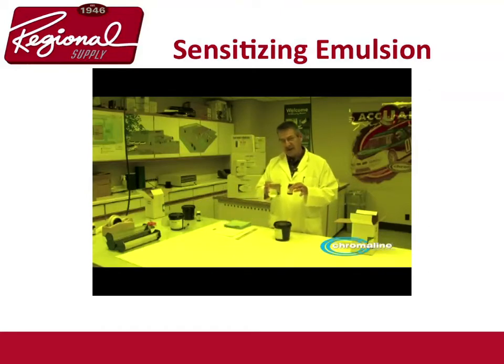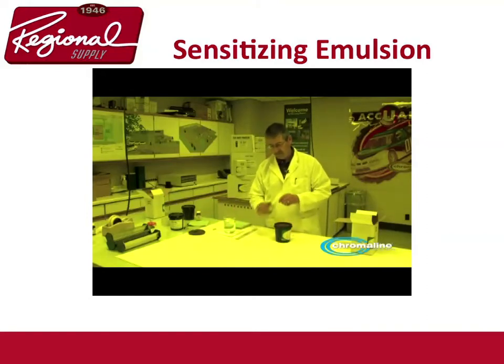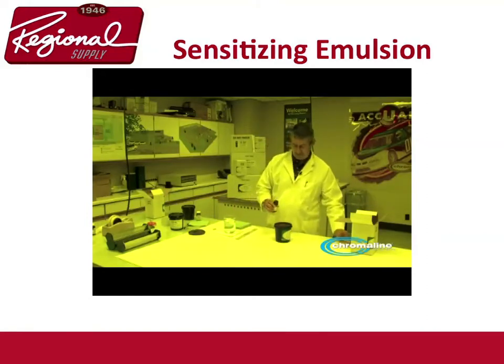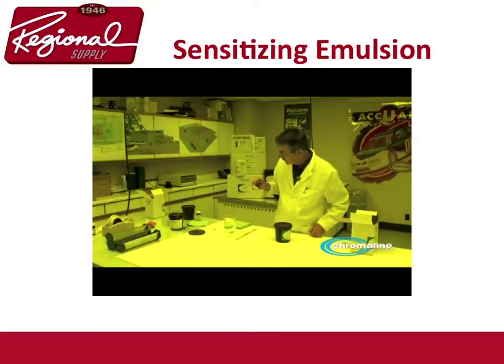First of all, I've added water to this diazo bottle. I've added water up to the shoulder, put the lid on real tight, put a rag over this and shook it. You want to shake it for at least 2 to 3 minutes to make sure the powder gets totally dissolved. Because if it doesn't get totally dissolved, you're not going to get it into the emulsion. Take the lid off and pour the emulsion in. Look inside to make sure there's nothing hanging on the side walls, that you got all the emulsion.